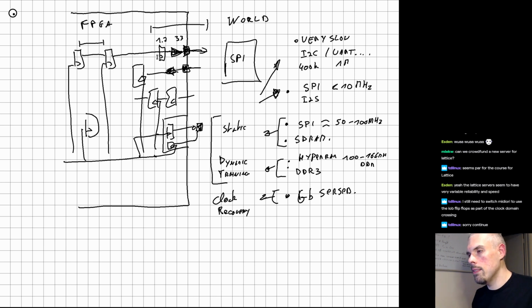And the way you can sort of forget about that from an I/O standpoint is that if you're talking to a device, you try to have all its I/O in the same FPGA I/O bank, right? FPGAs have different I/O banks. The iCE40 has 3, but really only 2. You have one that's on the top and one that's on the bottom of the FPGA.